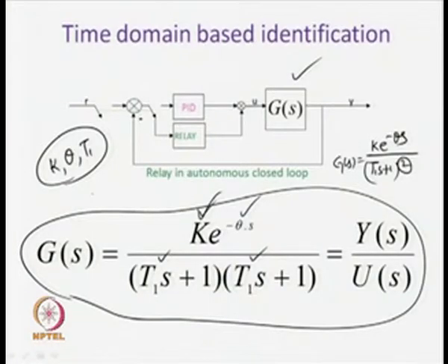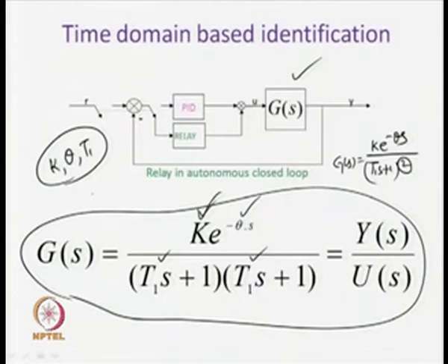So, we need to derive 3 analytical expressions that can be used to identify the model parameters. Now, where to repeat all those things and find 3 analytical expressions? If it is possible to use the previously derived general expressions, then our life will be easy. Effort will now be made to show that the state space representation of this second order plus dead time model with pole multiplicity can be given by equation number 2.